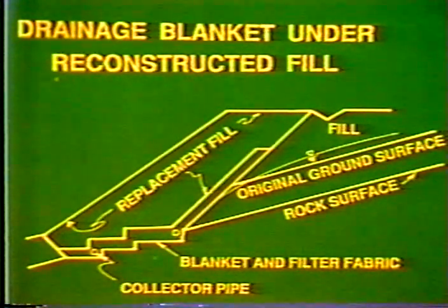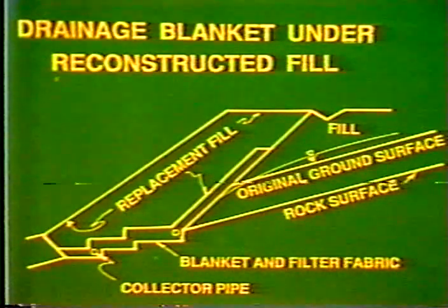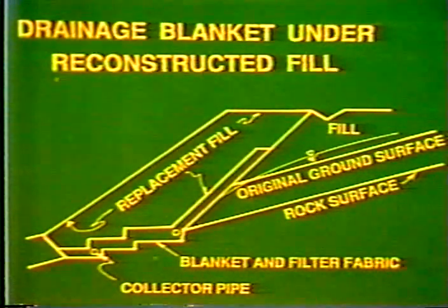Under replacement fill, again, maybe a little bench in there, as shown at the bottom, and use a drainage blanket. Run it up on the slope part of the way so that you can intercept any water coming from the groundwater surface there. Also, if you're placing the stone blanket against a clay or silty type material that has a lot of fine materials in it, here again you want to wrap it with a geotextile so that we can prevent the stone from clogging up.